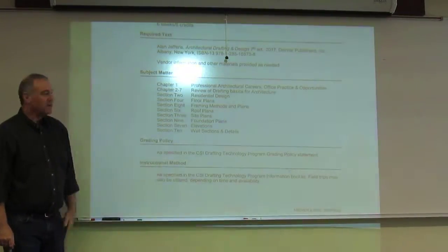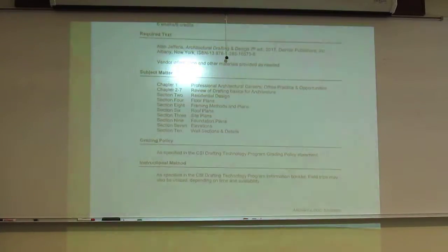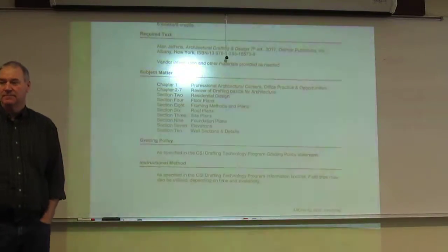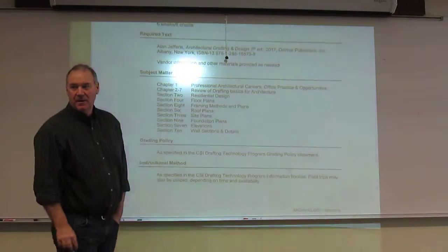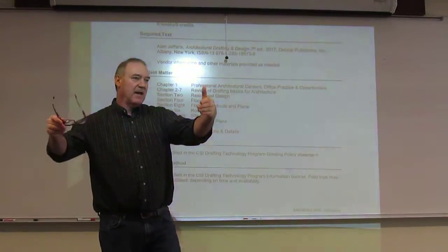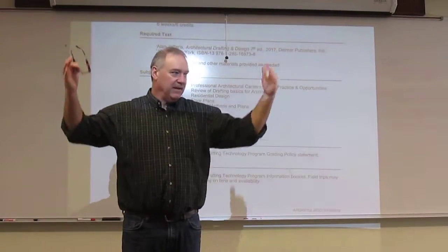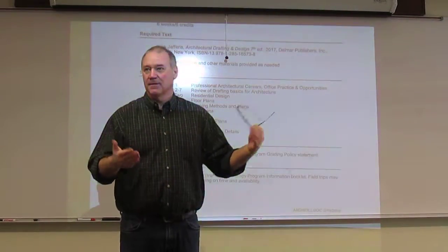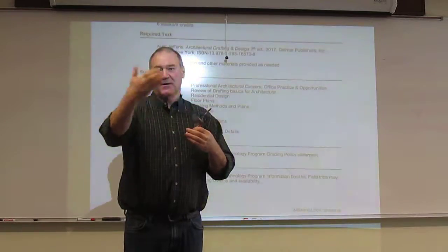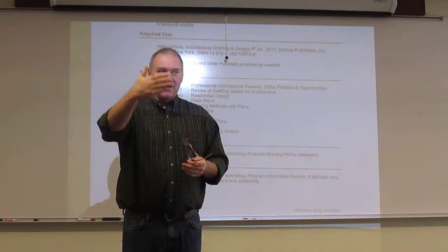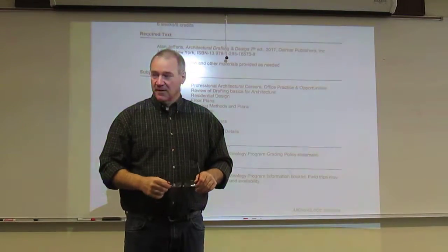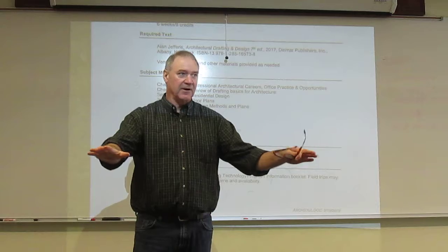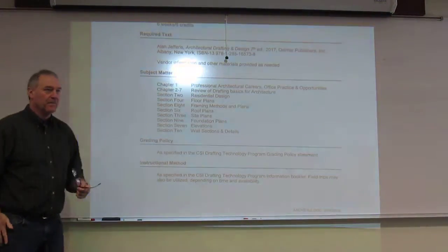We'll produce our elevations and any needed details. Yes? Why do you have to know the roof to do the foundation? Because you don't know how much that roof weighs. Or if I've got a big eave overhang, do I need columns? Do I need beams? What do I need where? Maybe I've got a roof I have to do an internal support for. Where's that bearing wall? I have to trace that weight down to the ground. We have to know where all those locations are before we start pouring concrete on the ground. Okay, that's why we do that.